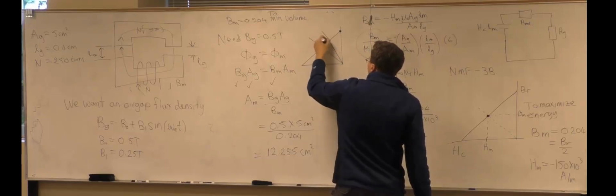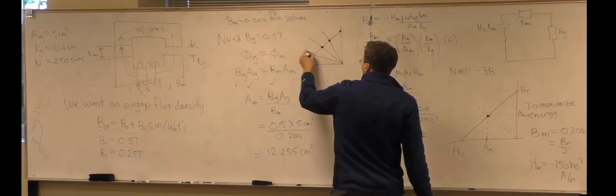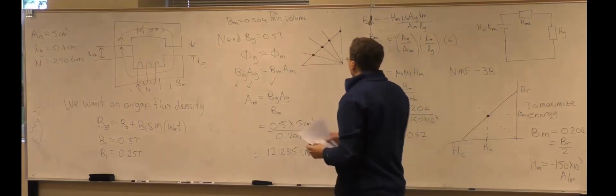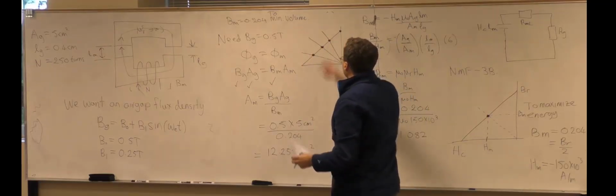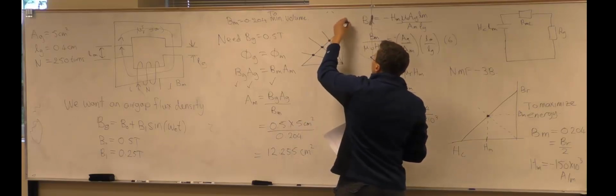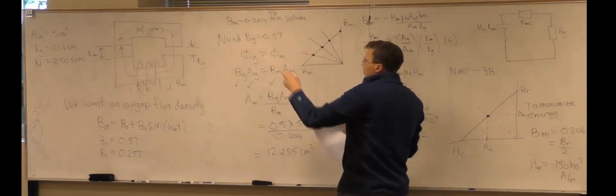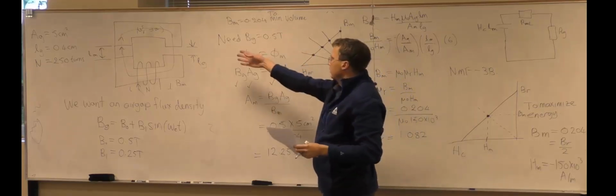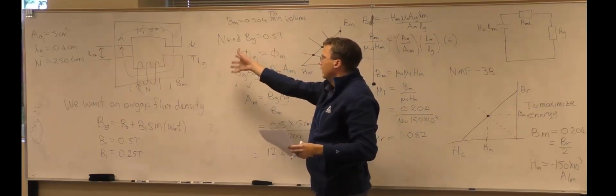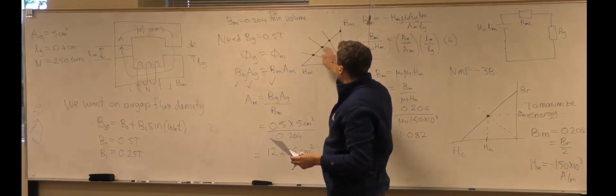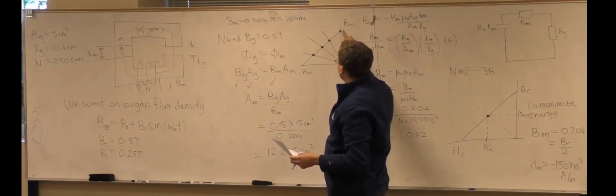It's going to determine where we are on the BH curve, and that load line is dependent on the material properties, and the lengths and the areas as we've derived. So we can't choose to be up here.